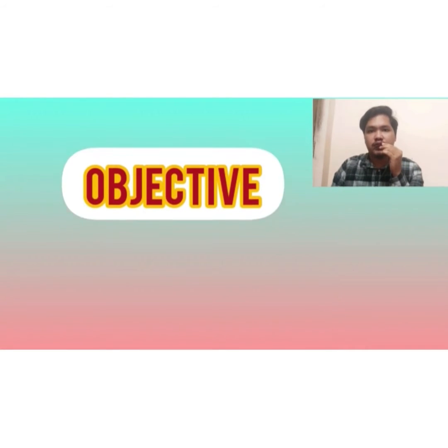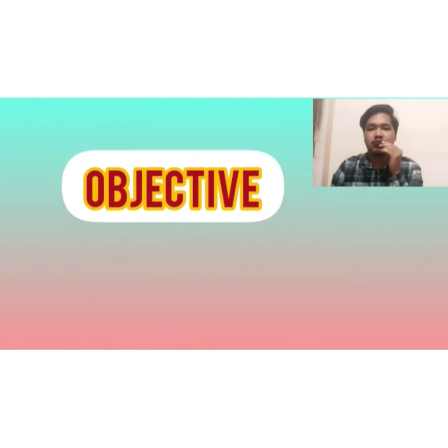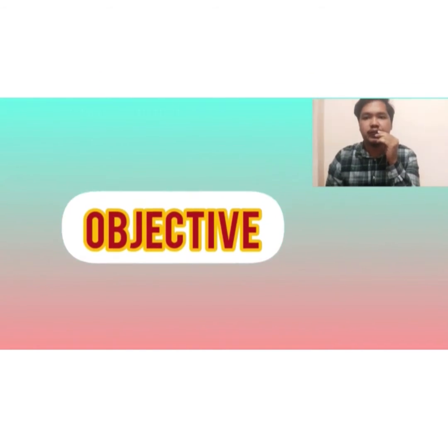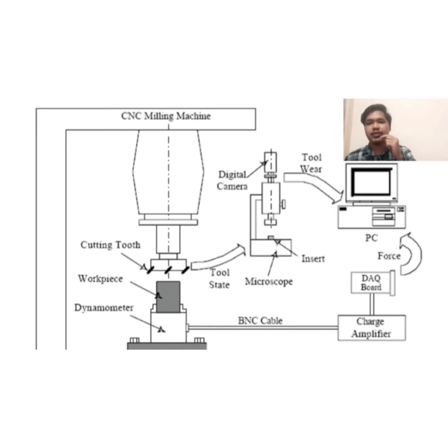The objective of this experiment is to sense the loss in original function of the tool in order to detect an abnormal state. The machine used to run this experiment is a CNC milling machine. So how does the machine work? The workpiece moves horizontally, driven by x-axis and y-axis motors, while the tool moves vertically, driven by the z-axis motor. There are sensors used in this experiment, which are a force sensor and a dynamometer. The dynamometer is used to measure torque and rotational speed.